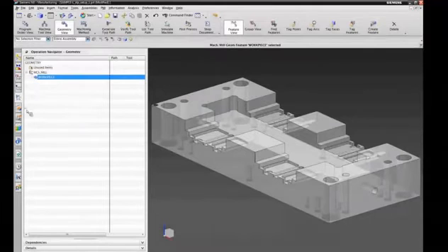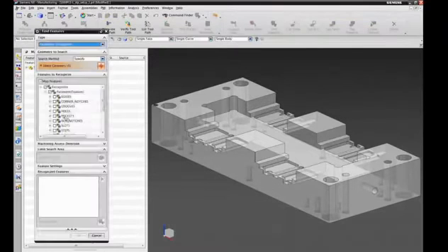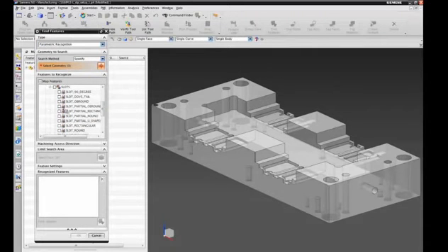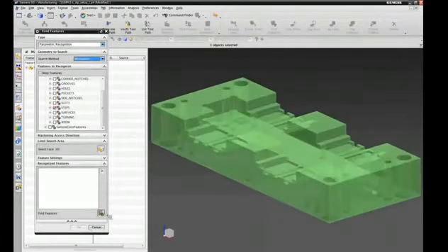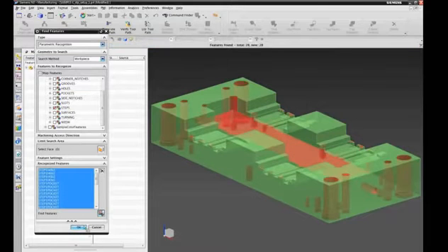Bear with me. And let's do feature recognition on a geometry like this. So bring up the Find Features dialog again. We've seen it before. I'm no longer interested in running WireEDM. I'm looking at the stepped features. Maybe I do a slot partial rectangular and no slots. It's okay. I don't have to do everything. Let's go find it. You will basically see it works fine on imported geometry as well. But there's a glitch, and we'll get to that in a minute.